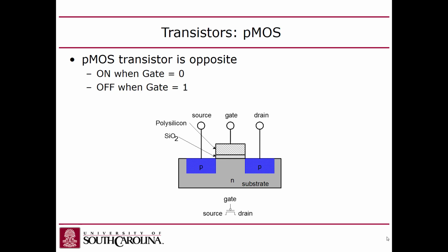If you look at the gate voltage relative to its substrate that's charged up, it's actually negative. So what's really happening with PMOS transistors is that they have a 700 millivolt threshold like the N do, but it's negative 700 millivolts. So you put a negative voltage above the threshold here to turn it on. You guys with me?